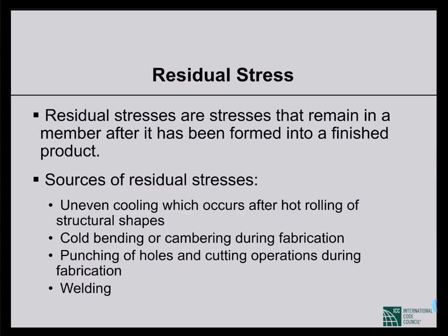You can understand, for example, if you have something in your hand and some part is cooling down very fast and some part very slow, you can feel that there will be stresses, because at some location it will try to contract, at some other location it will try to expand, and that will cause stresses internally. So that is the source of residual stresses, uneven cooling.